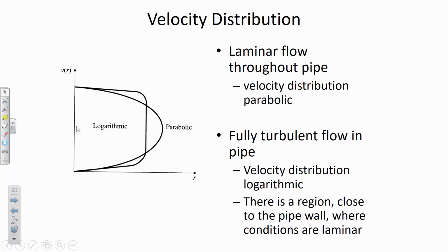And so this is the middle of the pipe, where there's the least amount of resistance, and if conditions are laminar, there would be a parabolic distribution of this curve. And then, of course, as you approach the top of the pipe, the other side, then the velocity is decreasing again until it reaches 0 at that top edge of the pipe.